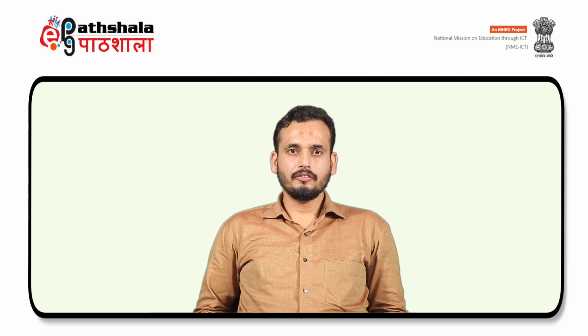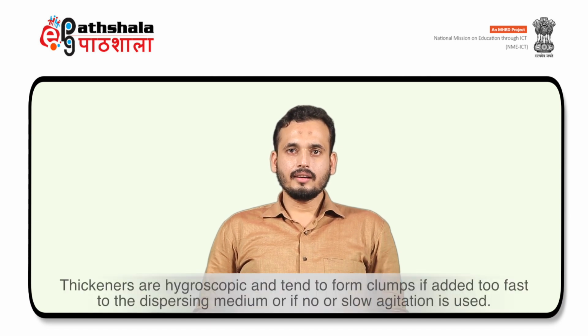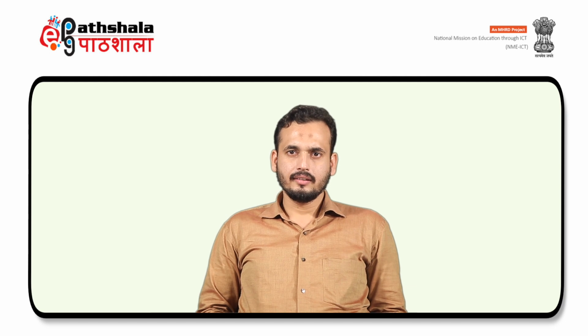During the formulation of a product containing a thickening ingredient, dispersion of the thickeners is a critical step. Thickeners are hygroscopic and tend to form clumps if added too fast to the dispersing medium or if no or slow agitation is used. Certain thickeners need pH adjustment, meaning neutralization, to reach their optimal viscosity. In such cases, the neutralizer should be added after proper hydration of the thickener in order to avoid clumping.